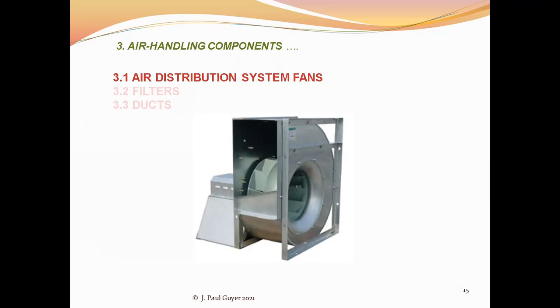And then the air handler also contains a configuration of duct that permits the system typically to exhaust some percentage of the return air that's being returned from the occupied space, exhaust around 25% of that, and then bring in around 25% fresh outside air.